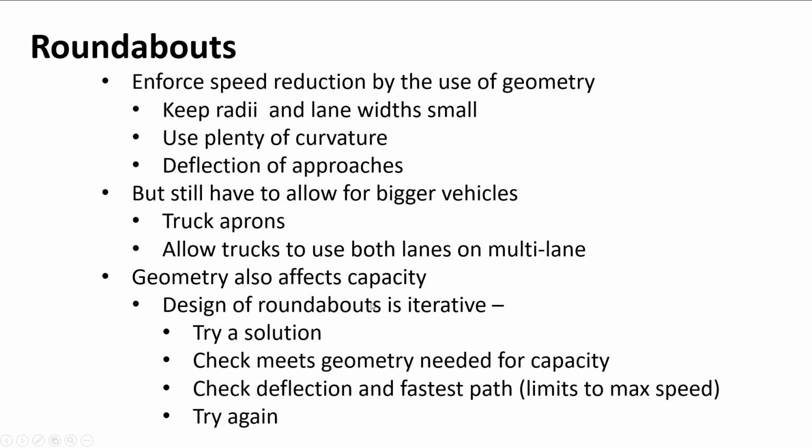All right, so geometry also affects capacity. The bigger the roundabout is, the higher the capacity is, but then the safety drops. And so there's always this real trade-off in roundabout design, which makes roundabouts an interesting one to work on, because they're very iterative. You'll try something, you'll check the speeds, and then you'll realize people can go too fast, so you change more than one of your curves, usually either the center diameter or one of the flares coming in, and the radii on the entrance, and you'll try to get that to match your speed goal for what your roundabout should be.